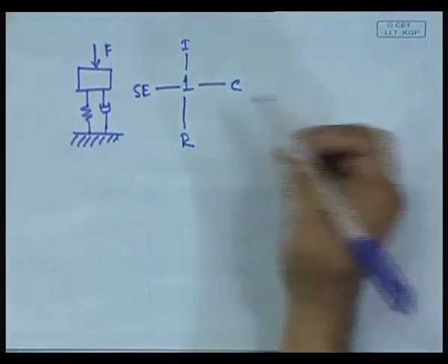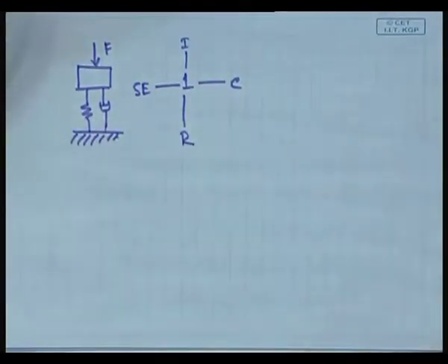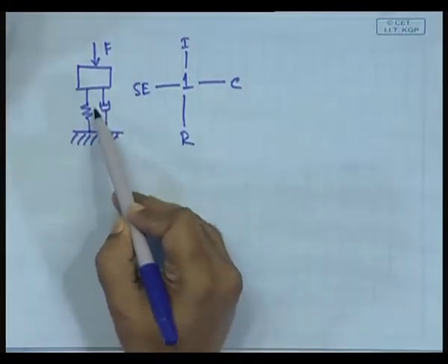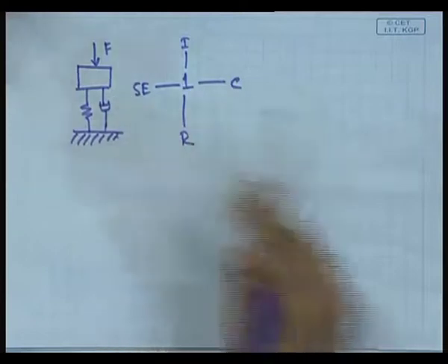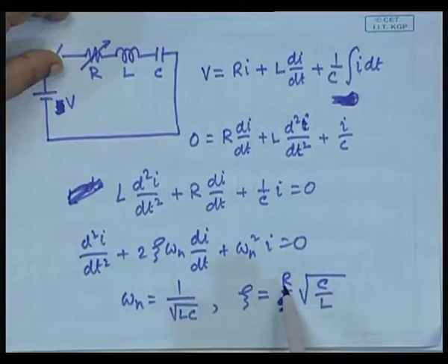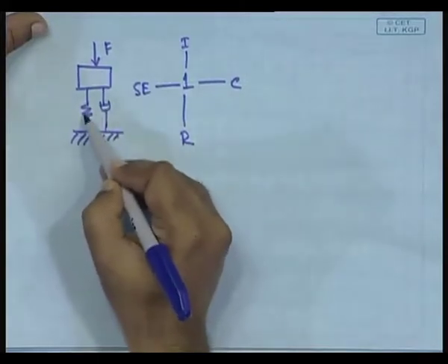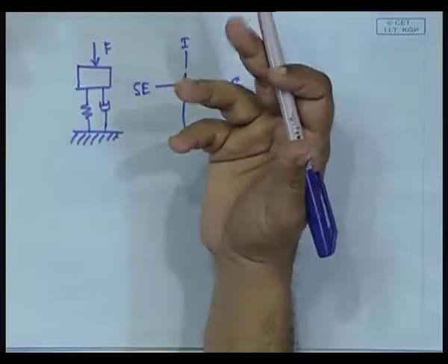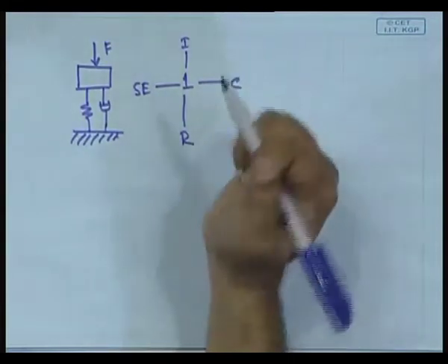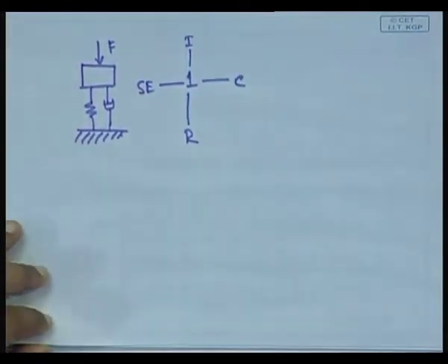Fine. So, this kind of a system's behavior will also be determined by the same kind of dynamics, and depending on the value of the damping, it will either be underdamped or overdamped. Not only on the value of the damping, remember it also depends on this term. So, if you keep the R constant and slowly increase the spring constant, then also it will exhibit the same kind of behavior. Clear? Yes, I knew that you have done the time constant business earlier, but nevertheless it was necessary to place it in a general format.